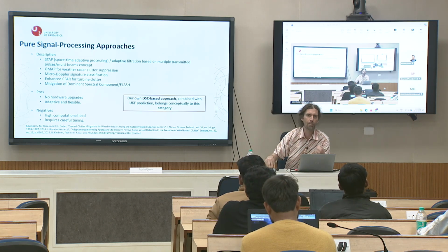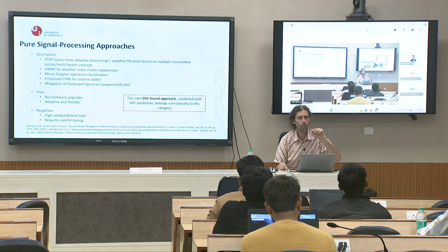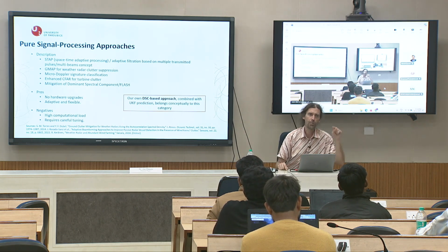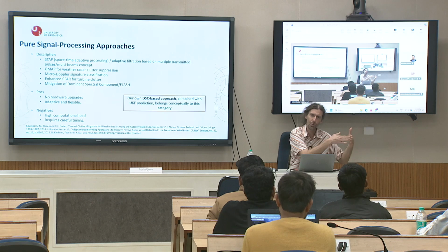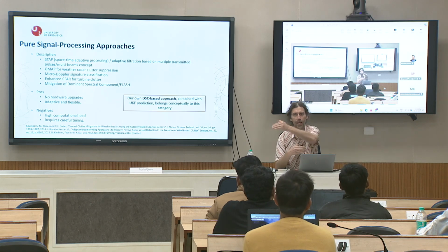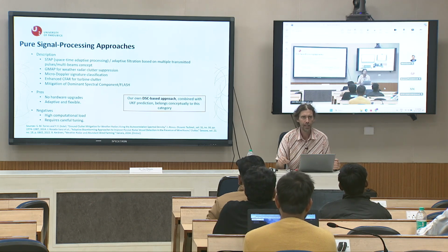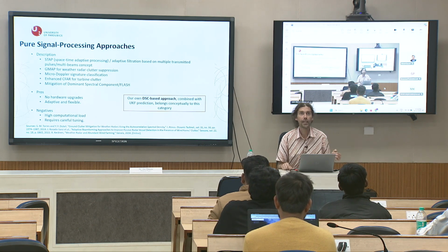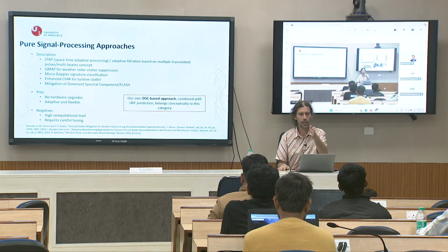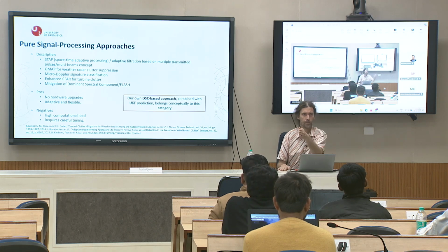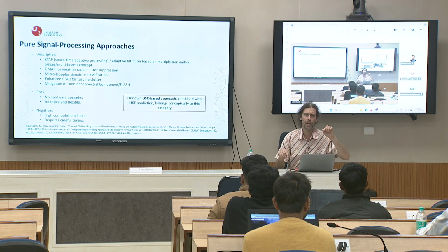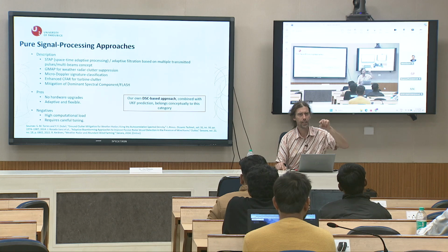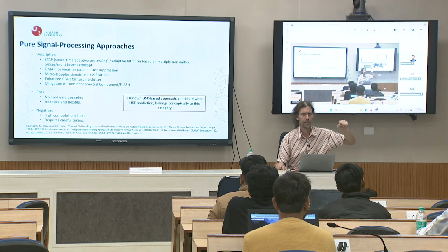And why do we call it microdoppler? Because this Doppler is relatively small in comparison with the Doppler shift of a plane, because of course it has high speed. So how can you recognize it? Doppler causes your central frequency to be moved, and microdoppler means that it will slightly change the spectrum, like it will be jittering.